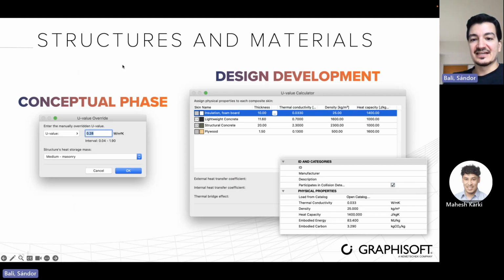Now, what I mentioned in case of the structures and the materials, previously we just had something that we made up, kind of, or what was not entirely made up, but what was required by the standards, local standards. Let's say the local standard says that the structures have to perform at 0.28, then we want to obviously fulfill that. Now, when we're using the actual structures, then we're going to have certain types of building materials with their own thermal conductivity and density, which physical properties are also defined in our building material settings. And based on these values, we're going to have a U value calculated.